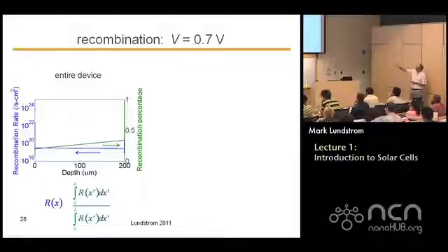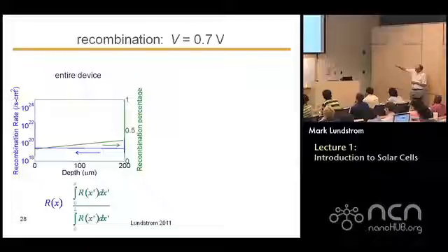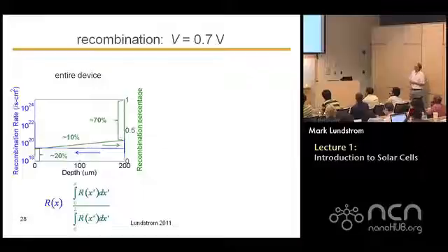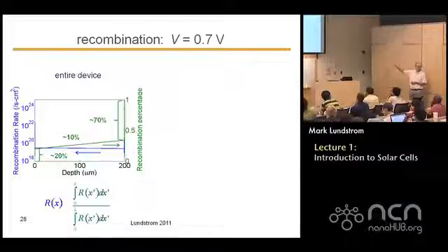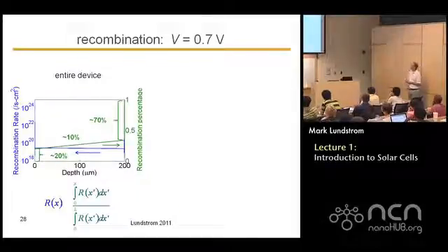The green line is the integrated total. Now, you can see that there's a bunch of stuff happening right at the beginning, in that first 0.3 of a micron that you can't see. And there's a bunch of stuff happening at the end, where it looks like the green line goes from 0 to 1. That's 100% of the recombination. You can see that an awful lot of the recombination is occurring at that back contact. That little barrier we put there isn't keeping the electrons away.